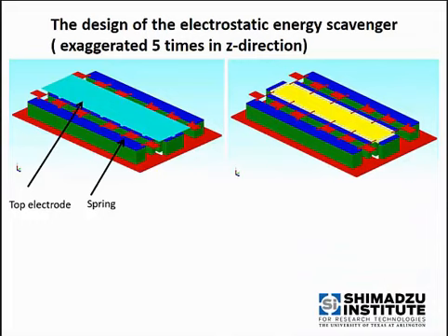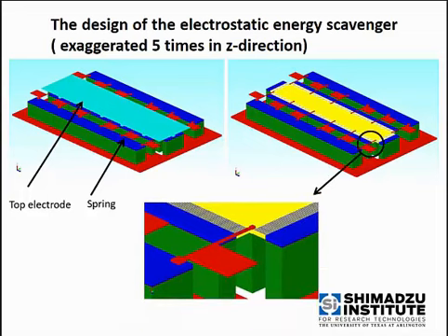Hiding the top electrode actually shows a clearer view of the proof mass, with movable fingers all around it. Zooming into this point shows us the movable fingers with the proof mass and fixed fingers coming out of the sidewalls. Overlap type capacitance forms in this area.